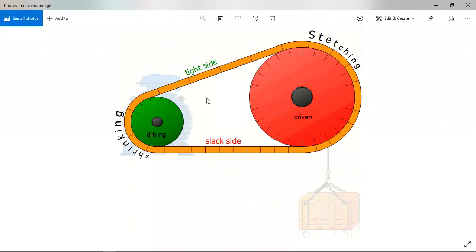That's to show that. And suppose the frictional grip between the driving pulley and the belt is not that much, then without carrying this belt, the driving pulley moves a little further distance. That is called slip.